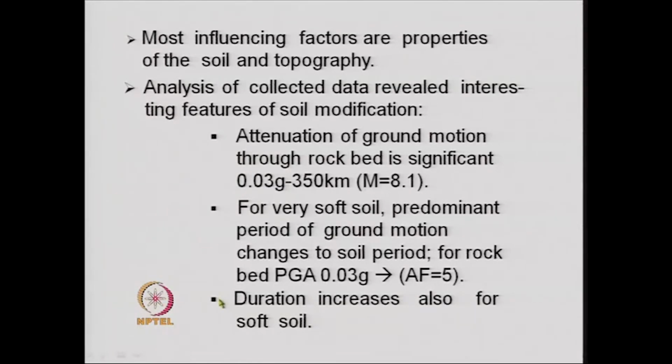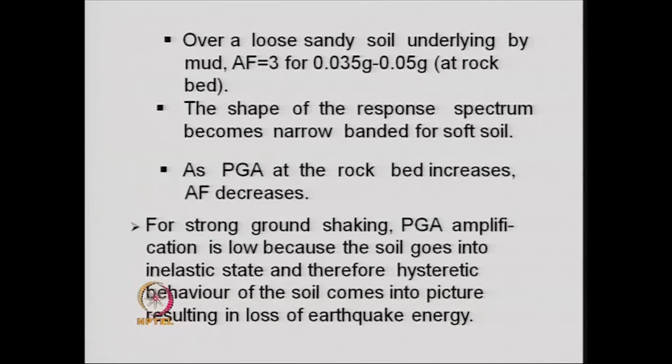Next thing that was observed was duration increases also for soft soil. Over loose sandy soil underlying by mud, the amplification factor was of the order of 3 for a ground acceleration at the rock bed of the order of 0.035 g to 0.05 g.